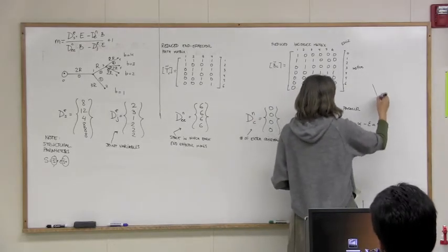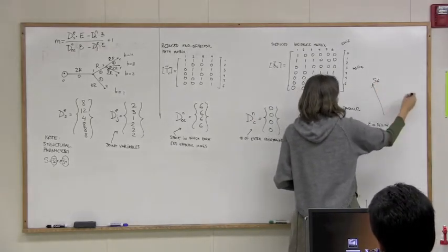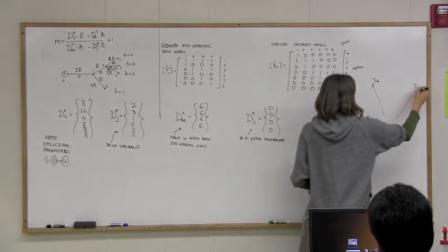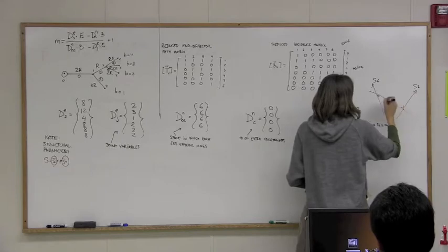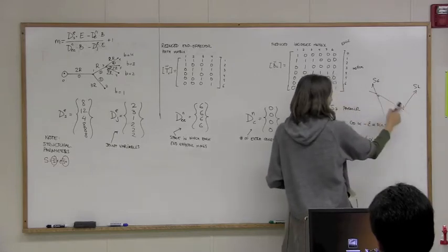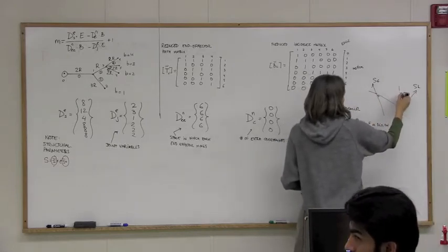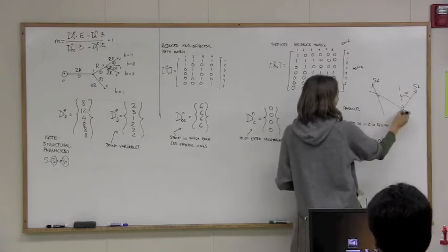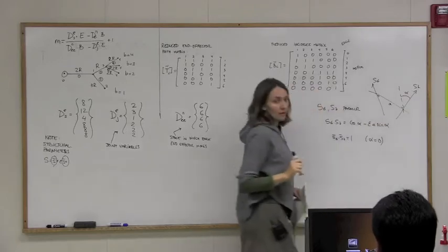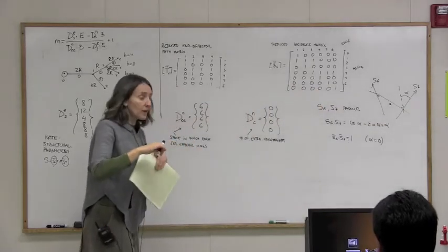Let me just write that again. So here you have S6. In general, they are skew. And then you look at the common perpendicular line, right? And then when you do the dot product of this, you get the cosine of the angle between them, and then minus the length times the sine of the angle between them. That's what the dual dot product gives you.